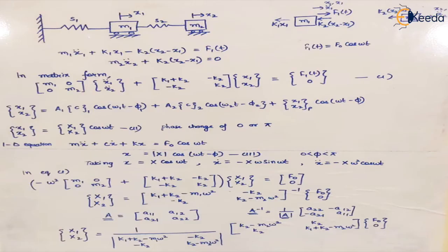Now we have already studied a body with a single dimension, or 1 degree of freedom. Let's assume there is a mass m attached to a spring with stiffness s, and some force is applied in this direction. The equation of motion we used to get, with a damper also added, involved m x double dot, the acceleration of the body in this direction, because this is the direction of force, displacement, velocity and acceleration.